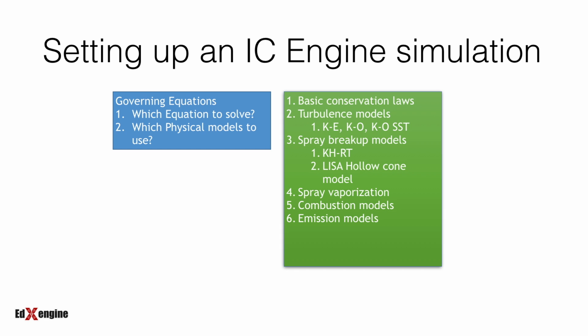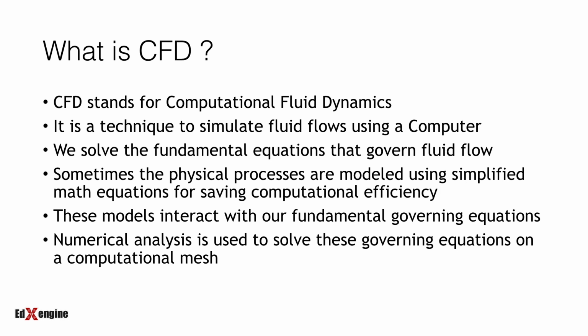In addition to that, if fuel spray is being simulated, then the appropriate spray breakup models and spray vaporization models need to be used. For getting the correct combustion characteristics, the right combustion models need to be chosen, and to get the emissions right, the right emission models need to be chosen. This is why a CFD analyst should be a subject matter expert and also have knowledge about fluid mechanics, numerical analysis, and CFD. So now, what is CFD?